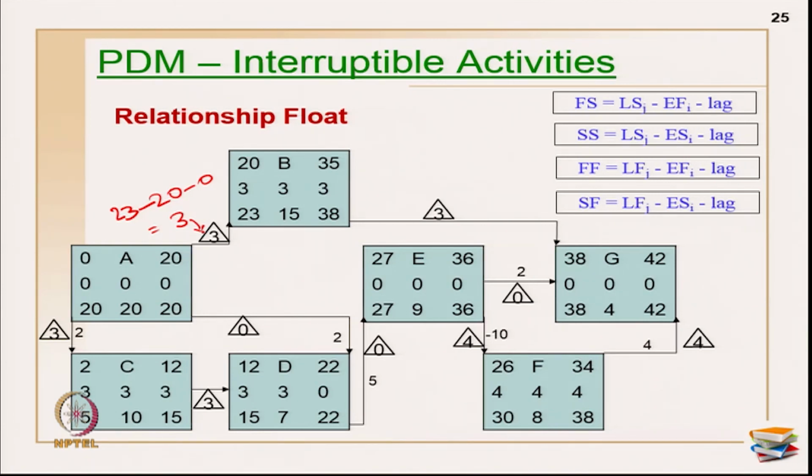Okay. Now, again I am going to show on start. So, this is a start relationship. Primarily you have to take it with the successor. So, I am having a relationship. This becomes my successor and this becomes my predecessor. This is represented in J form, this is represented in I form. My arrow is stopping here, this becomes my J, and this becomes my I for this particular relationship. LS of J, late start of J is 5, minus early start of this activity is 0, minus the lead or lag value given as 2. So, this becomes 3 for me which is written here.